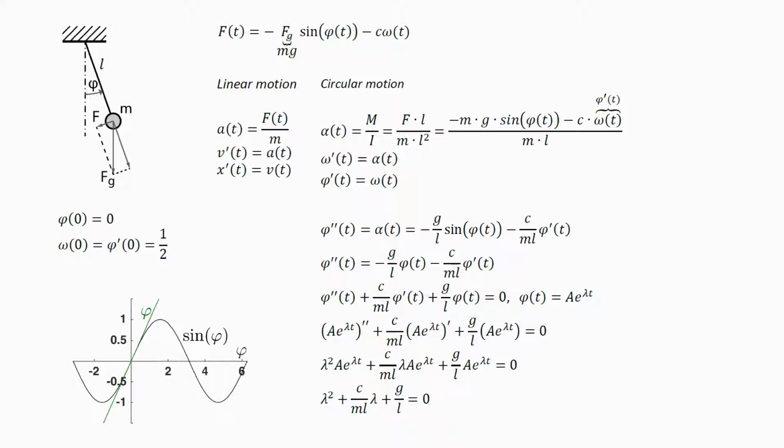A simple mechanical system that I will start with is this pendulum. This pendulum has length L, mass m, and its angle is denoted as phi. The gravity force acting on the pendulum I have denoted as F sub g. This gravity force I can decompose into these two components. This component does not really affect the pendulum, only this one does. So to describe the movement of the pendulum I need to be able to express this force.